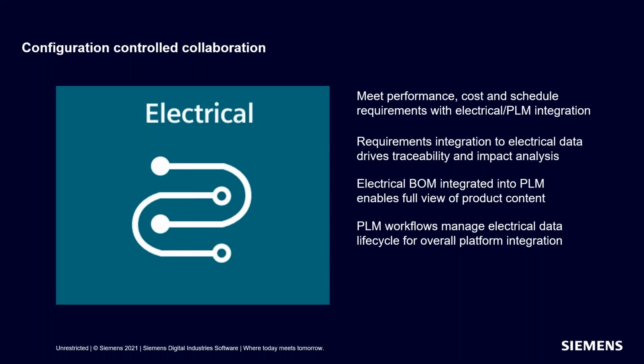One key output from the electrical design process is a fully defined harness down to the specific part numbers for every component, including things like terminals and plugs that must be fit into or onto the wire ends and inserted into connector cavities. This full harness content BOM can be published to Teamcenter, where it can be consumed into higher level BOMs or used to feed the ordering and manufacturing process.